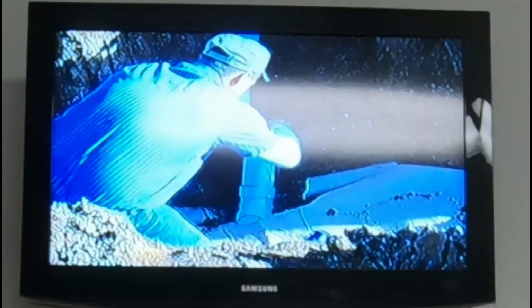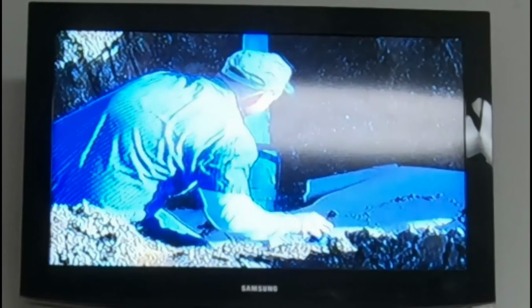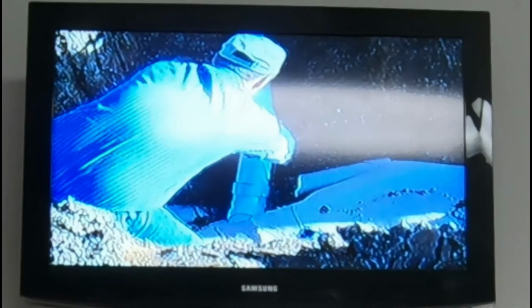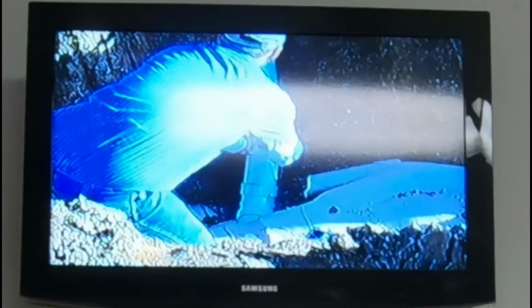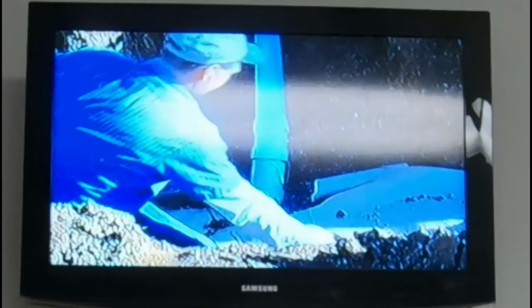A minimum of 6 inches to 12 inches of earth cover is required over absorption lines. The maximum earth cover shall not be greater than 24 inches unless special conditions are noted on the permit. Schedule 40 PVC or equivalent solid pipe and fittings with sealed, watertight joints shall be used for horizontal and vertical changes in direction or grade and to cross under roadways or paved areas. Sections of solid pipe shall not be considered in determining the total absorption trench bottom area.